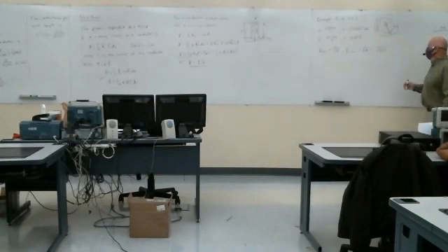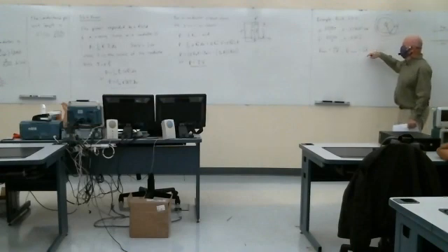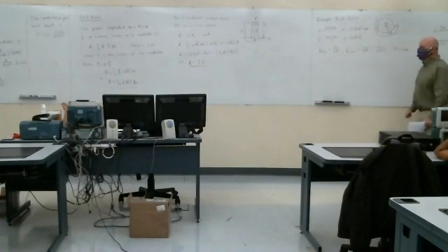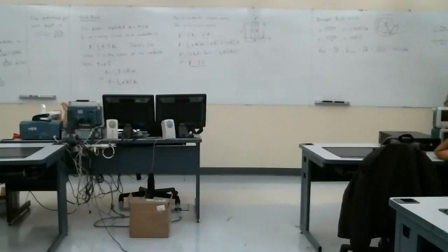For the inner conductor, it's a perfect circle, so that cross-sectional area is just pi times A squared. So at this point, we've got all the information we need to calculate this resistance, and it's 163.7 milliohms per meter, R prime.